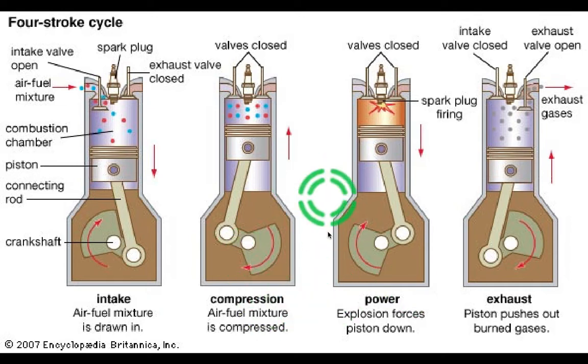I'm emphasizing this so much because in future lessons, when we discuss the camshaft, we'll be dealing with this subject. The camshaft actually completes one revolution in one cycle, right? So it rotates at half the speed of the crankshaft to complete one cycle.